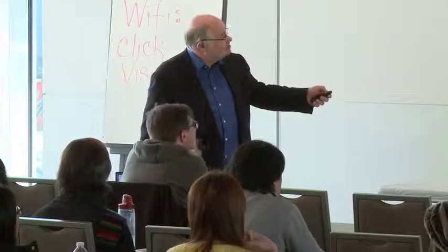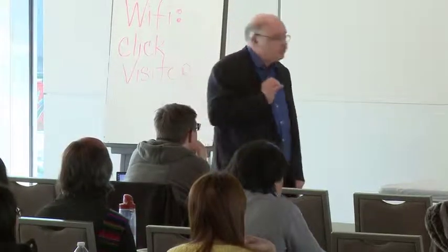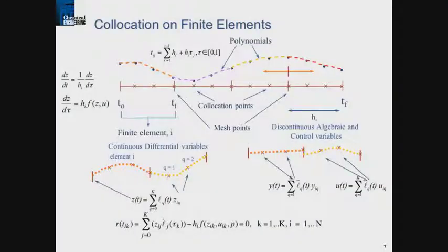And so what we want to do is use that well-known principle of thinking about boundary value formulations rather than initial value formulations, okay? This is written down as an initial value problem, or can be, and frequently treated as such, but if you want to embed that within an optimization problem, it's really good to think about that within a boundary value formulation. And so this is where we use direct transcription. What we do is we discretize the profiles, the differential algebraic equations in time, using an implicit Runge-Kutta discretization, a Gauss form, in this case orthogonal collocation on finite elements.